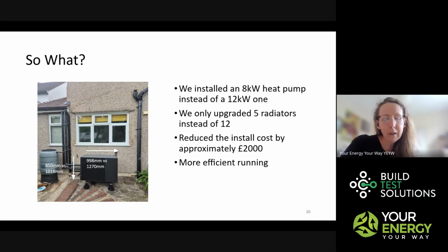I wanted to have a little look at the running efficiency of the heat pump to show you something, but unfortunately, these customers keep their house at 17 degrees. By choice. It's not that the heat pump can't heat it properly. So although I do have data on how it's running, and it's running at a very nice SCOP of somewhere around the 4.8 across the year,